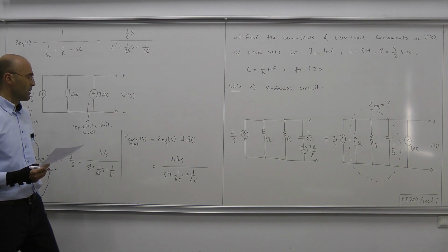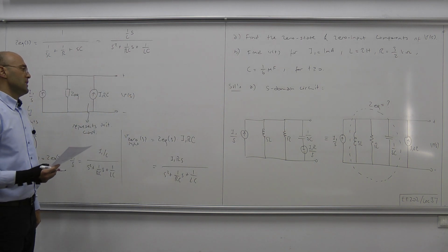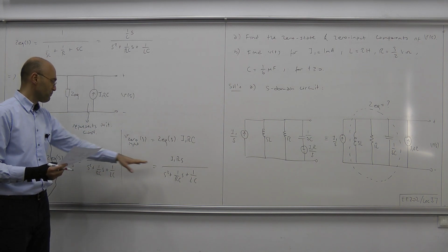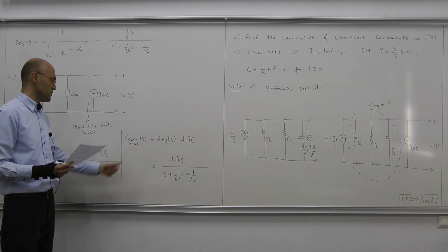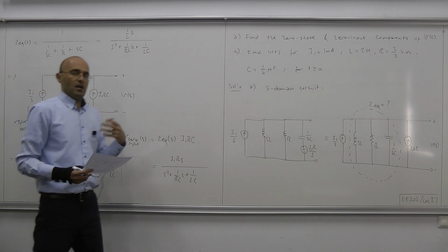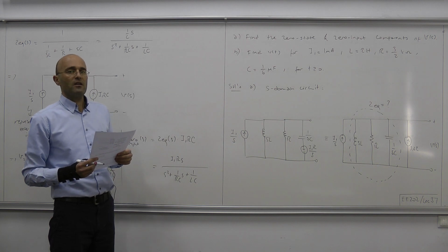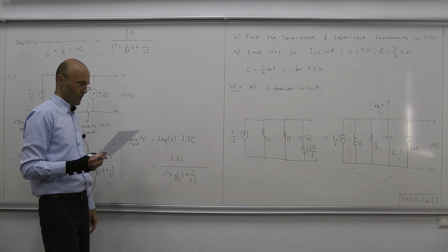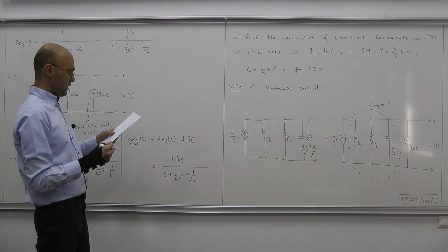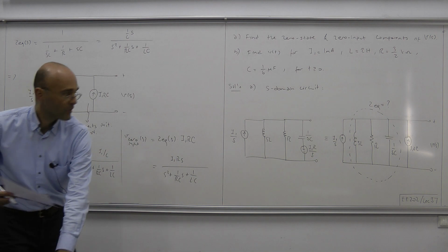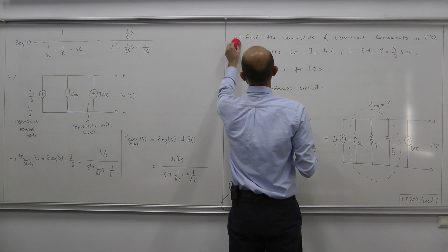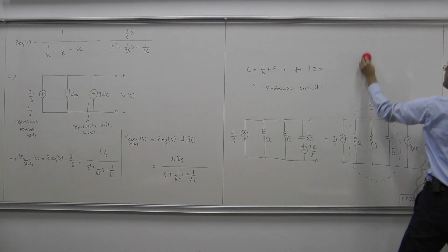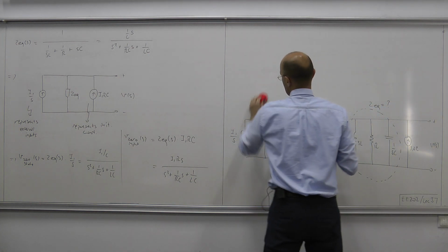Okay, and hence, since superposition principle is valid in S domain, by combining, or summing, these two pieces, zero input and zero state, we obtain the overall response, V of S, when everything is considered at once.